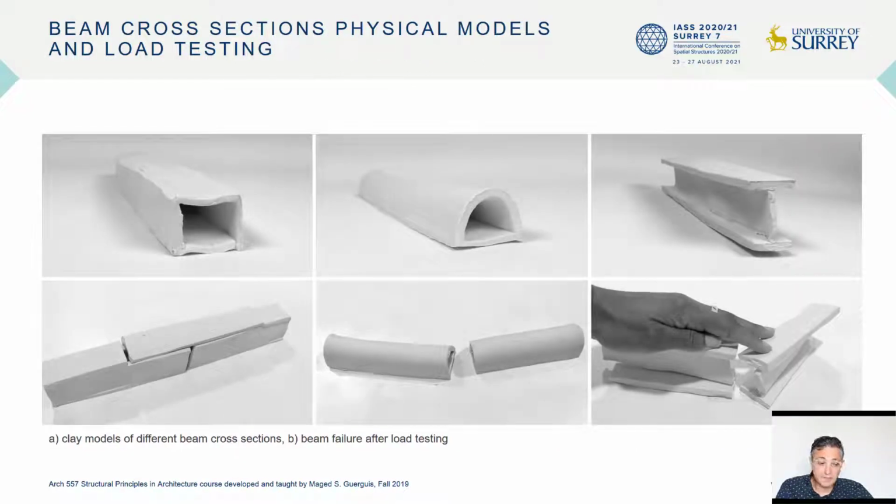Physical models demonstrate the findings from the previous exercise and allow the students to investigate the performance in relationship to its cross-section. Test results confirm that the wide flange section profiles perform the best, since they have the most material concentrated in the flanges with the greatest possible distance from the neutral axis. This activity introduces the students to the physical load testing procedure in the course.